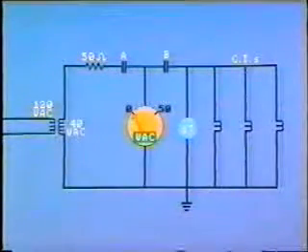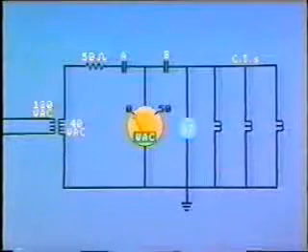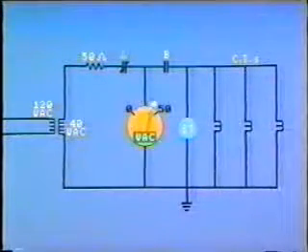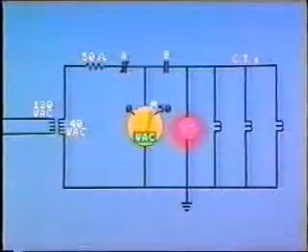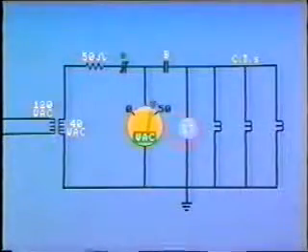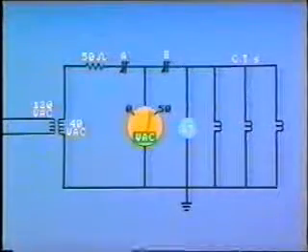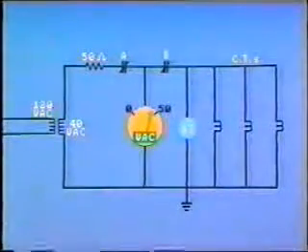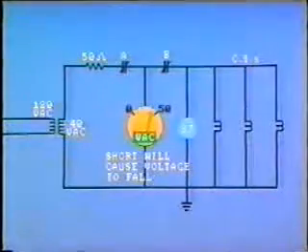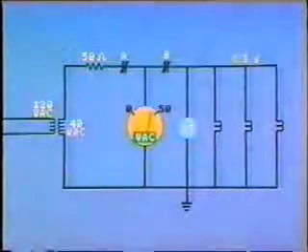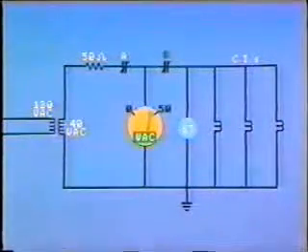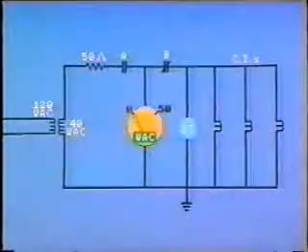This test circuit applies a low voltage to the relay circuit. When on standby, contact A is closed and 40 volts test voltage is available. Note that this is not sufficient to operate the high impedance relay. Contact B is closed to check for short circuits. A short in the CTs or the relay causes the voltage to fall. To check for open circuits, leave contact B closed and open contact A. The voltage should be 0. Check this one in your workbook.